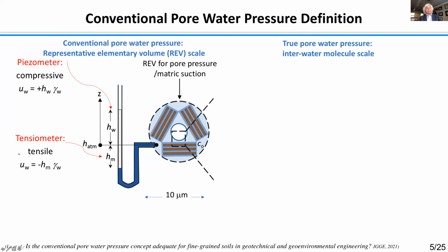Now, if we have a soil with a certain bulk concentration of chemicals, for example sodium chloride, potassium chloride, and so on, we can even measure what we call the osmotic pressure. If we put a semi-permeable membrane there, it has the ability to let the water molecule, which is about 0.3 nanometer, pass through, however it blocks the larger cation and anion chemicals dissolved in water.